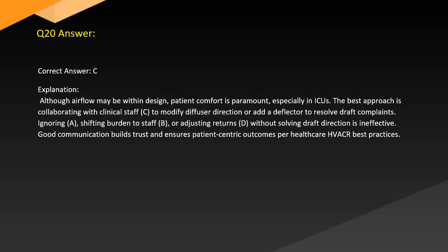Answer. Correct answer: C. Explanation: Although airflow may be within design, patient comfort is paramount, especially in ICUs. The best approach is collaborating with clinical staff. C. To modify diffuser direction or add a deflector to resolve draft complaints.